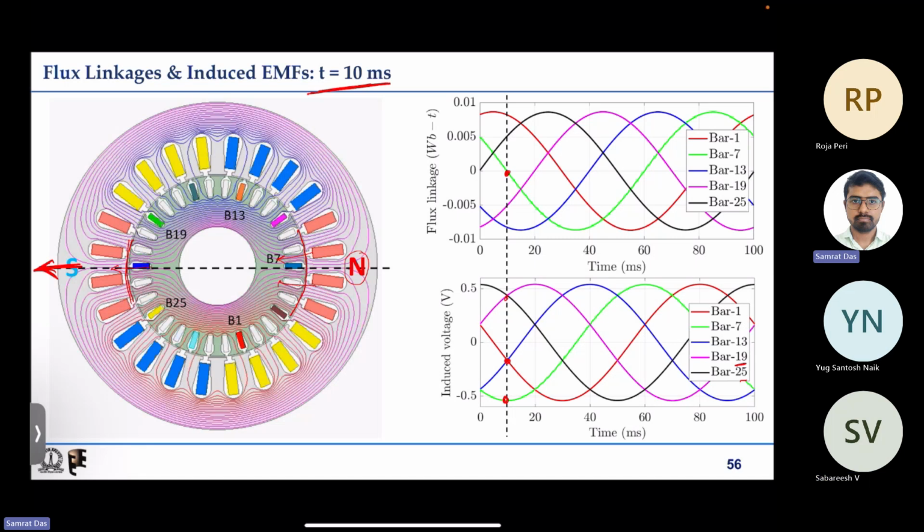No, as you know, the induction generator is not self-starting, so it requires some excitation. If it is connected to the grid, that can be taken from the grid, but if it is a standalone generator, then you have to provide some capacitive reactive power into the induction machine in order to start it. Those issues are often discussed in books and induction machine courses.